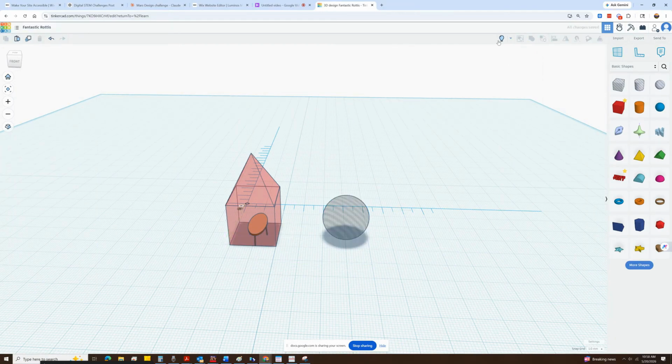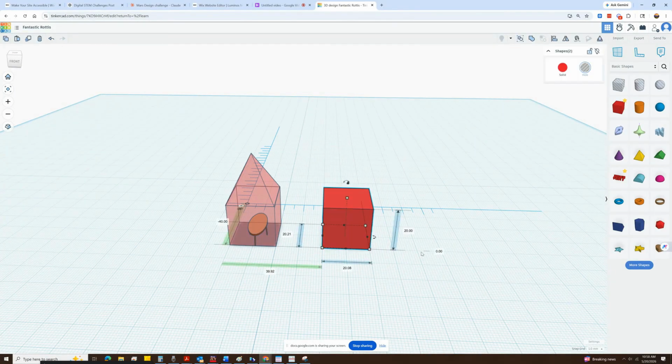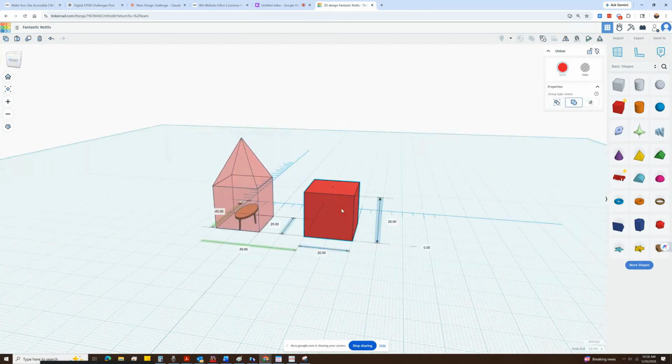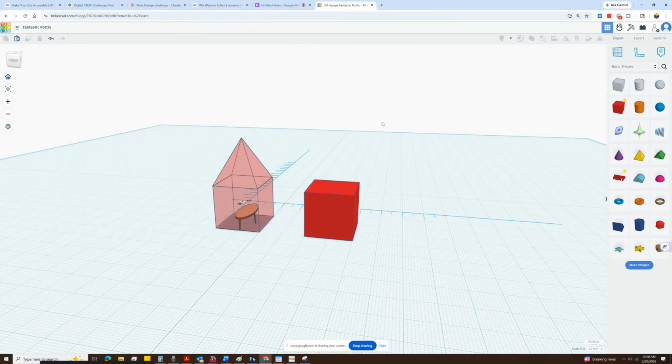Okay, so now I unhide all objects. Then I select the cube and the sphere together, and then I say union. When I do union, you can see that there is a hole created inside my cube. But we can't really see the hole because the sphere was completely inside. So we are unable to see the hole. So what should we do in that case?